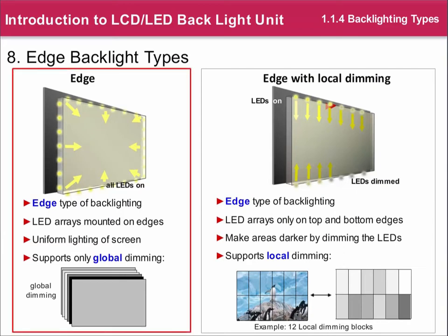The left-hand side backlight construction has been in use for a long time with CCFL tubes. Dimming was not an option with CCFL tubes. After we started using LEDs, dimming is possible and allows us to dim the brightness per each subsequent frame. We can even go further when we arrange the edge LEDs in blocks. We can control each block independently. This allows us to vary the backlight brightness locally by dimming certain LEDs.